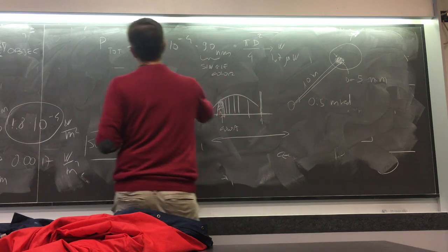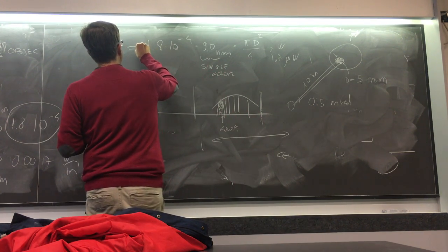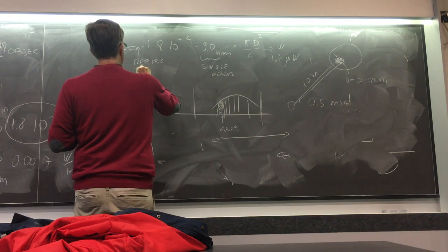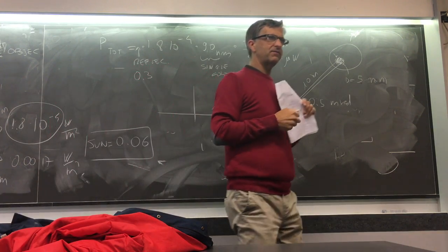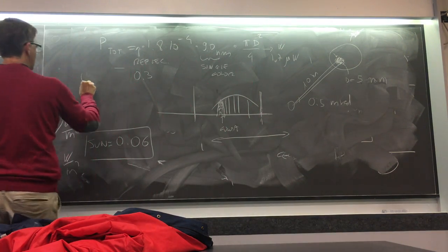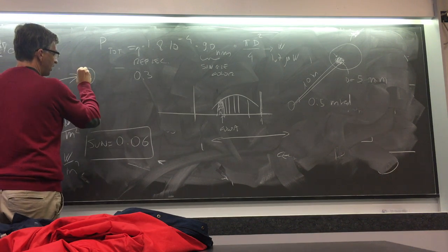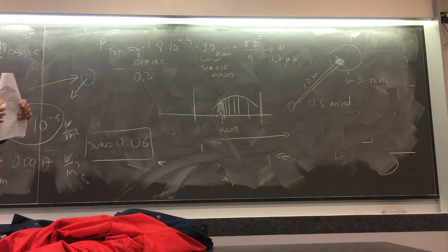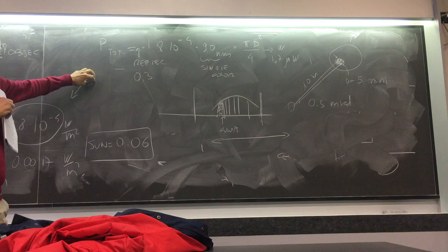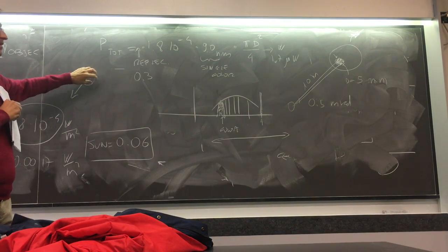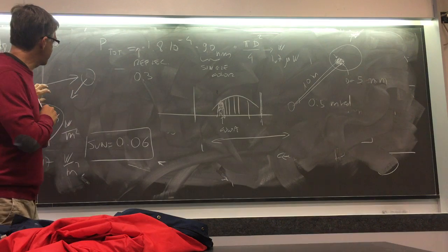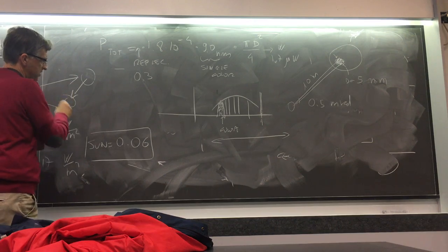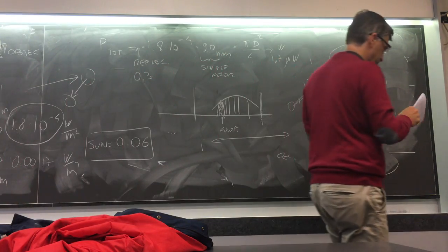Well, I remember I forgot to put an attenuation, that is the reflectivity. So this is already considering a 0.3 reflectivity, because here, in order to compute the power, I consider that not all the power that gets to the surface is sent back to you, because it's not a white body, but a partial white body, a gray body. I put a factor of 0.3, which says that only 30% of the power goes in your direction. That is, let's say, an average good value.